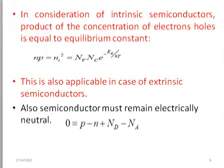Whenever you multiply the number of electrons with the number of holes in an intrinsic semiconductor, you are going to have Ni squared, where Ni is the intrinsic concentration. It can be electron and it can be hole. And we have seen in our first lecture that N times P, or Ni squared, is given by NV NC exponential minus Eg all over kT.